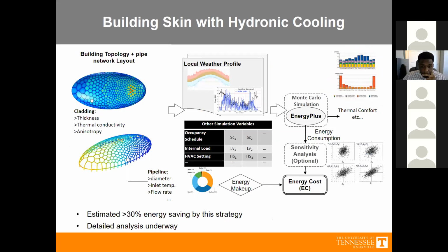What we have done with that is hypothetically design what we call an active cooling building envelope by passing water into the skeletons of, for example, building facade panels. Those skeletons are active cooling water lines and at the same time serve as the structural frame for those facade panels. We have run some preliminary analysis to see how we can design the pattern distribution, for example, for a glass dome, based on the hotspots that happen during the daily solar cycle.